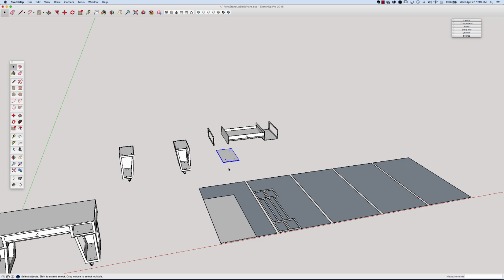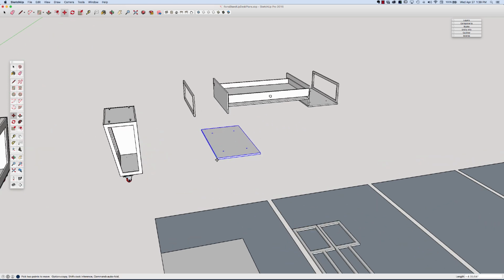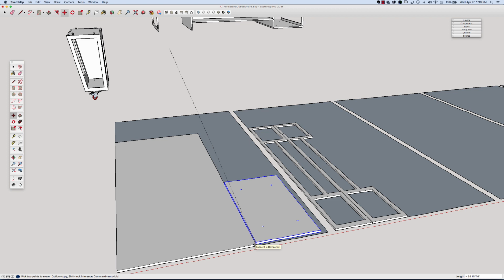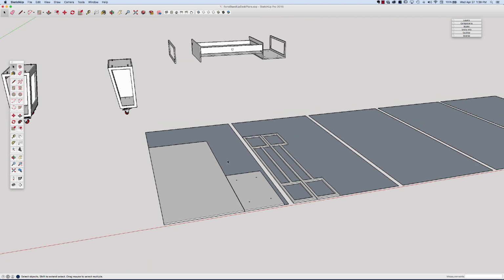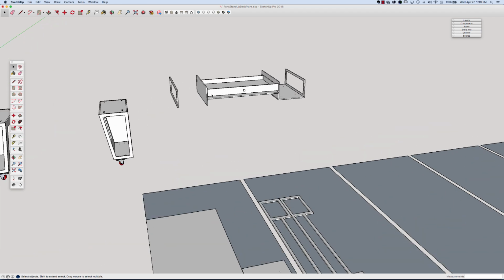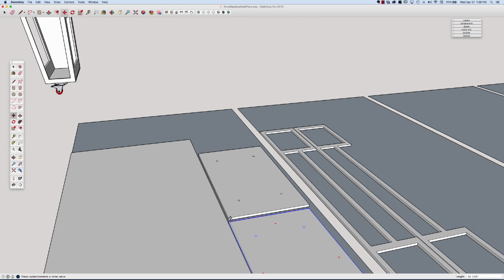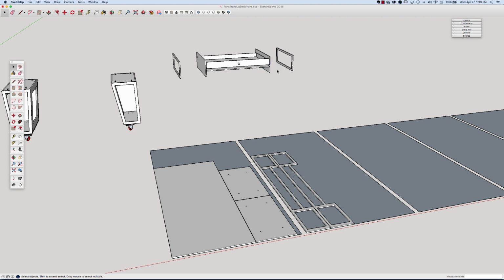All right, so then I'm going to take this and put it on the plywood. And again, it does fit there, so for now I'm going to put it there. Move it over that 1/8. And I'm going to make a copy of it. Move. Tap the Alt key. You don't have to hold the Alt key, just tap it. Coming up and butt it right to that piece, and then move it 1/8. And then come back up here and delete that piece.